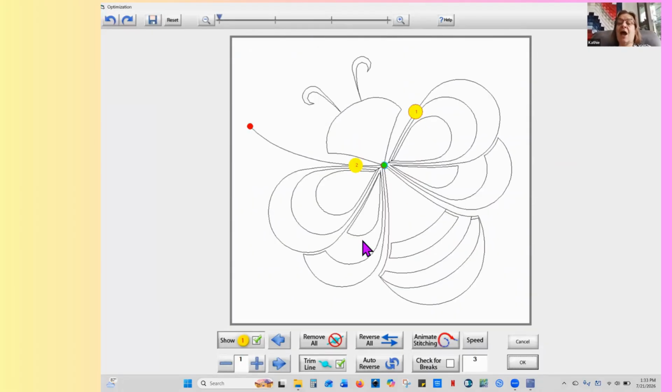Well, we can see that now we don't have a continuous line, but we also don't have a jump stitch. What we have right here is a break in the pattern. And I can fix this two different ways, so long as there isn't a jump stitch. A jump stitch would have a blue dot and a line attached with it. I only have a break. It means that when I drew this line, it didn't automatically attach to the other point that's right here.